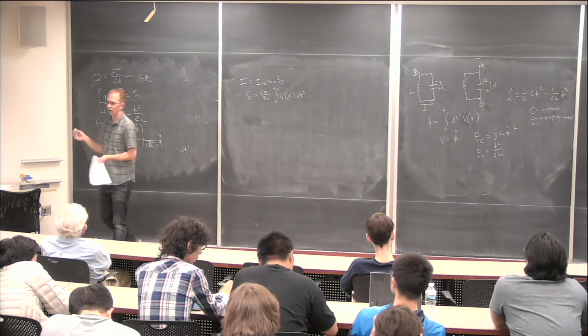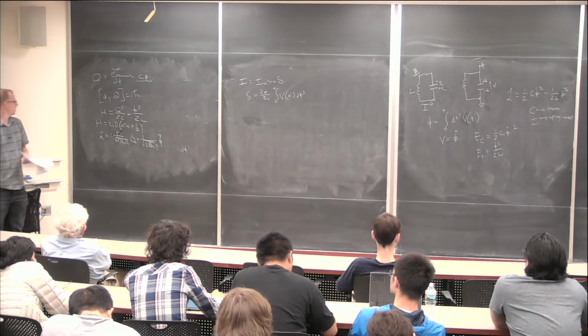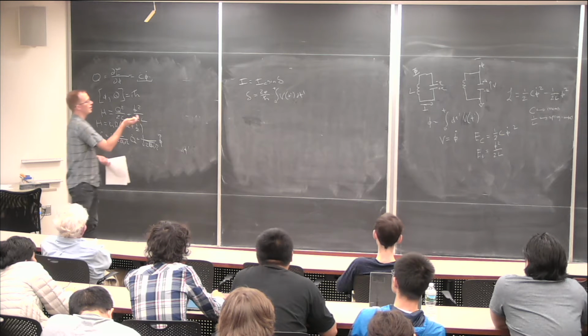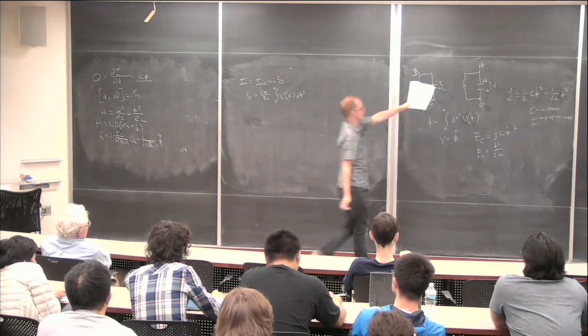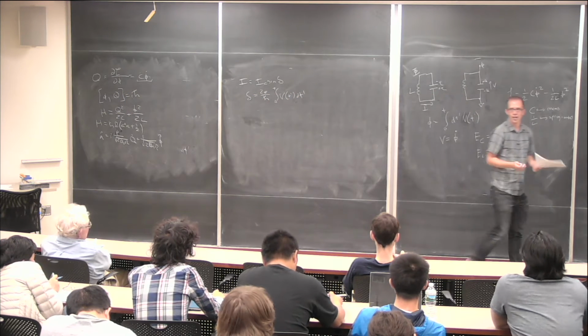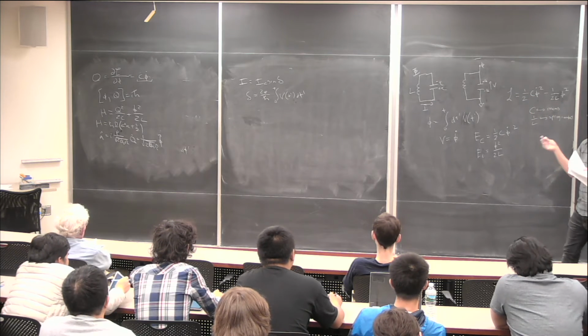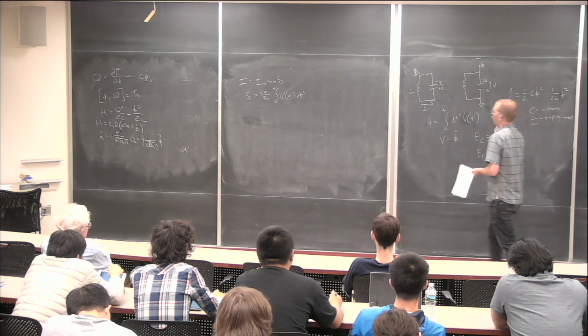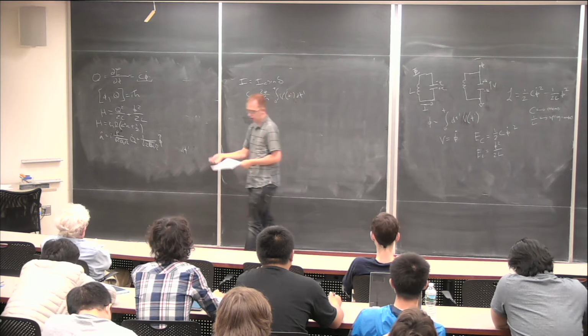this phase difference across the junction looks a lot like the flux that we encode in an inductor, and like our branch and node fluxes that we define in order to quantize our circuit. The fact that the phase difference across a junction is essentially a flux is why we prefer to work in this flux basis rather than in the charge basis.